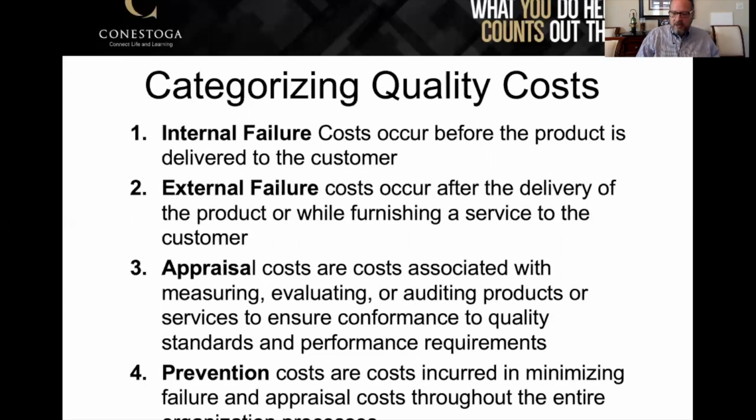If I'm doing electronics on a circuit board, and I wait till the boards come out of the reflow oven, it's too late. I practically can't do anything about a component issue at that point in time. Yes, you can micro solder and have somebody go through and pull things off and test them, but the cost of having somebody do that would outweigh the benefits of doing it. So by that point, if you have an issue, it's scrap for the most part.